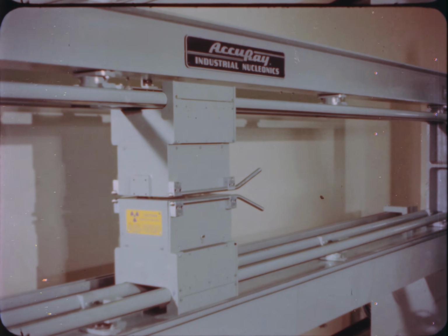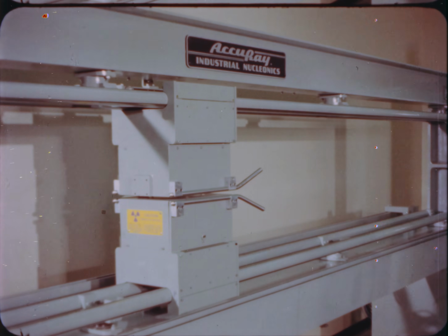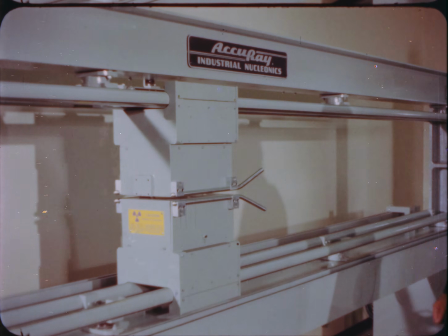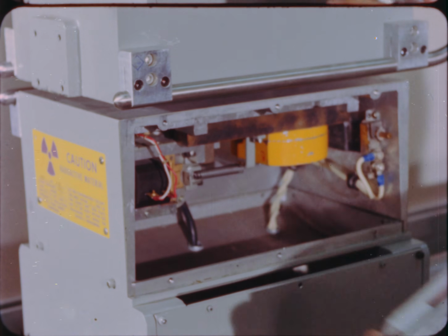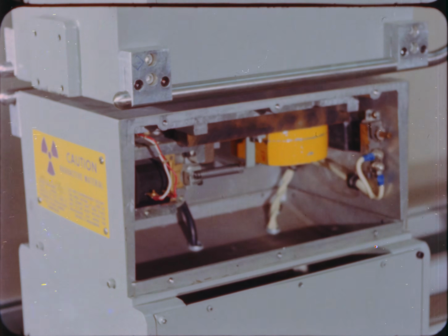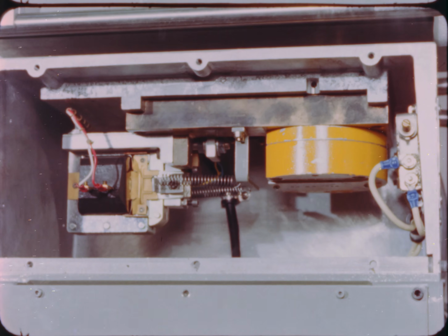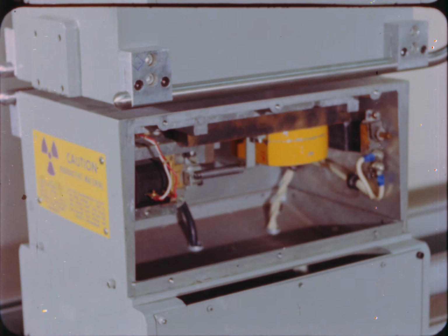This typical radioisotope gauge contains many safety features aside from its ruggedness and reliability. The gauge is made tamper-proof by its locking device. Any attempt at tampering shuts down the system and activates an alarm. The hermetically sealed and well-shielded capsule is mounted in a carrier, which is brightly colored and marked as to its content.